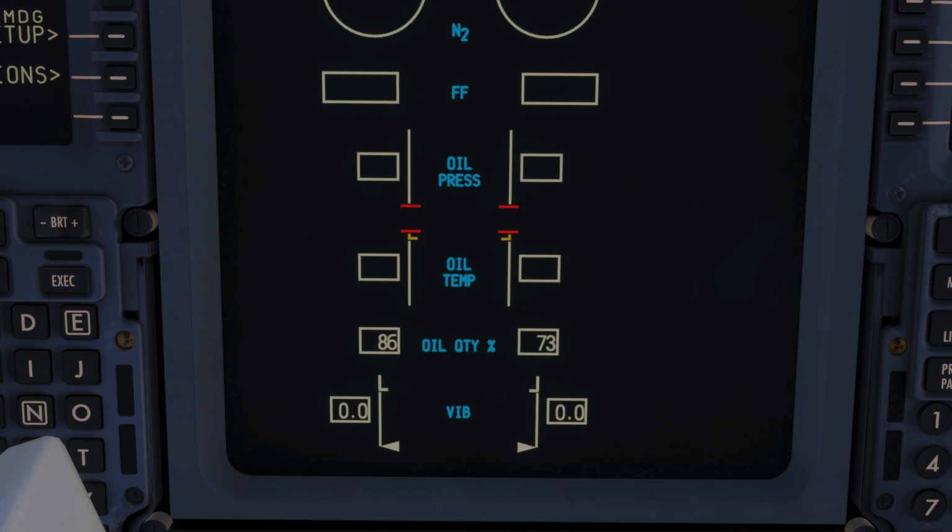But since the oil is in between the moving parts of the engine, the oil is getting hot instead. Therefore, the temperature of the oil gives us an idea about how well everything is running in the engine, and gives us an idea of whether the friction is getting too strong, which in turn can indicate problems with the bearings, etc.